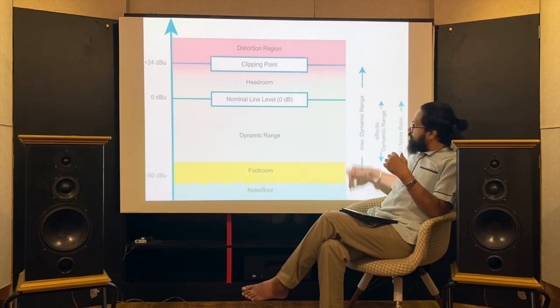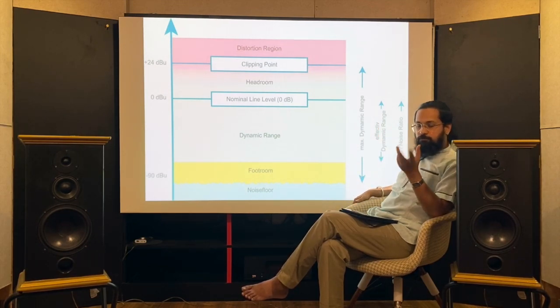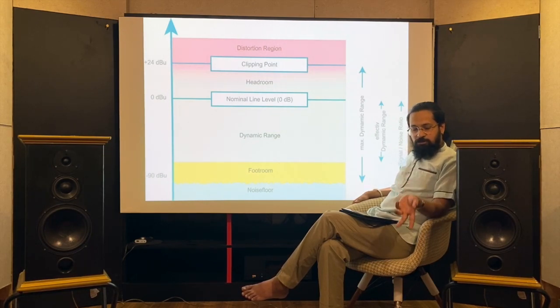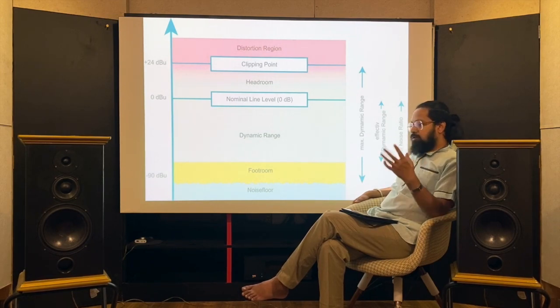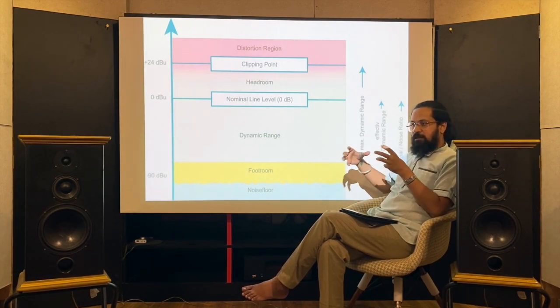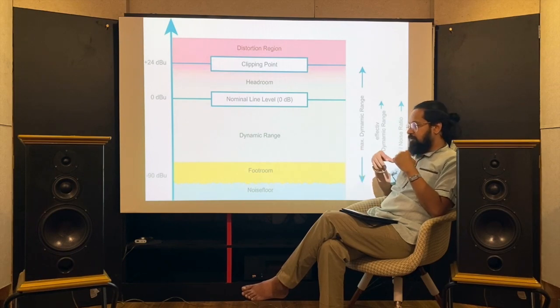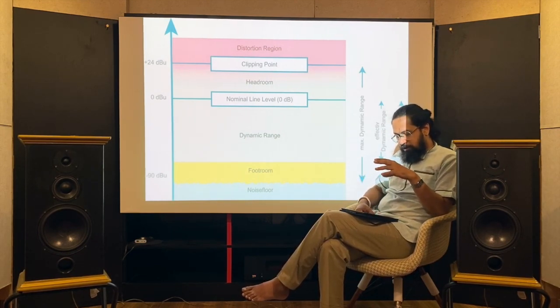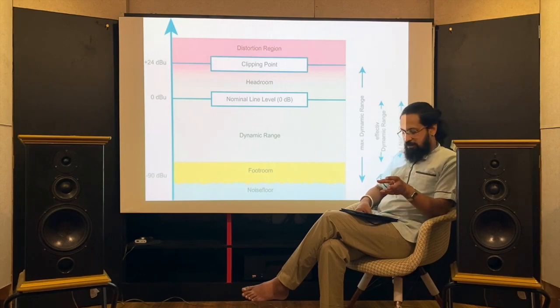This signal to noise ratio is really important when you are buying any equipment, especially the amplifiers, preamplifiers, and the DSPs, the DAC, digital to analog converters. All these points in your signal path impact a lot in terms of signal to noise ratio. So I think I have covered most of the points related to the dynamic range.